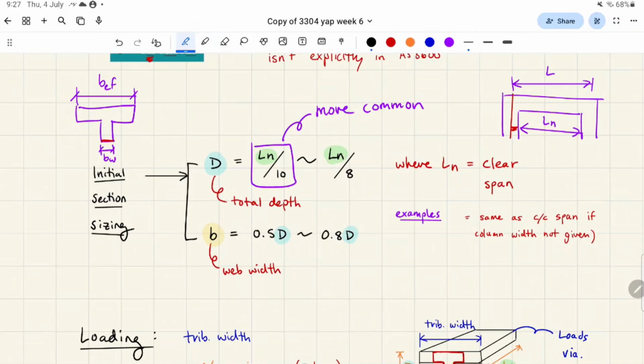And in the workshop examples, there's basically 3 questions to do with flexural design, and in question 1, you don't design the concrete, you just design the steel, right? Like how much steel you need. In question 2, they take the initial guess as 0.7 D.